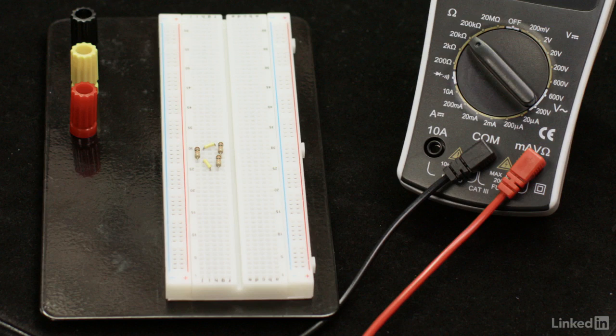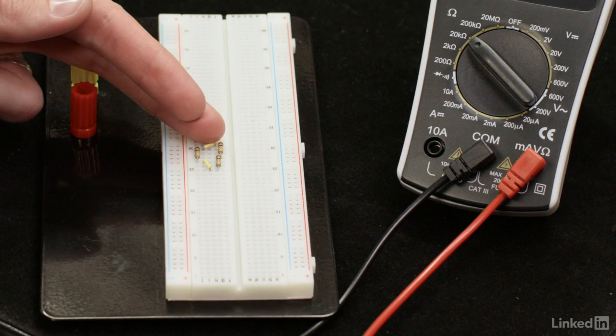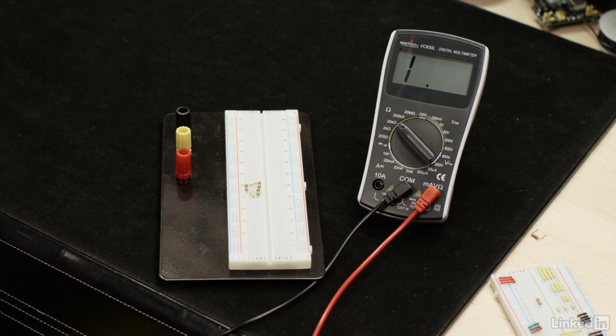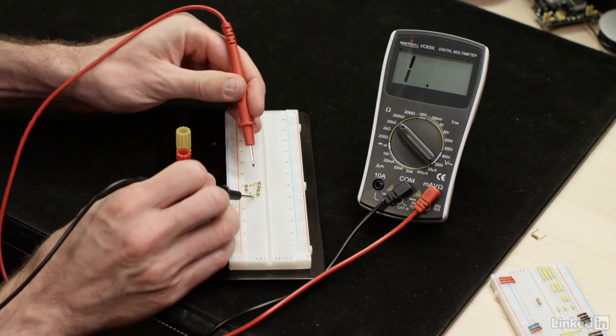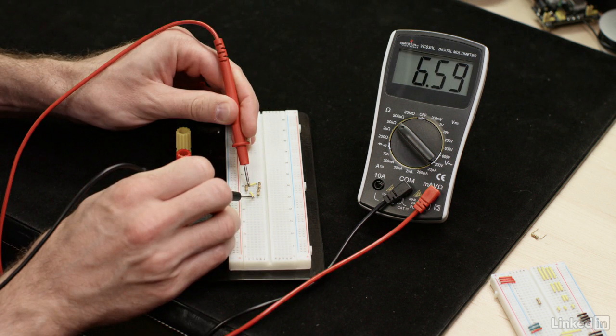The best way to check my math is to actually measure the resistance of these two resistors in parallel using my DMM. I've placed a 10 kiloohm resistor in parallel with a 20 kiloohm resistance on my breadboard, and since 20 kiloohms is not a standard resistor value, I've combined 2 10 kiloohm resistors in series to create that 20 kiloohm resistance. When I measure these resistors with my DMM, I see that the total resistance across them is around 6.6 kiloohms.